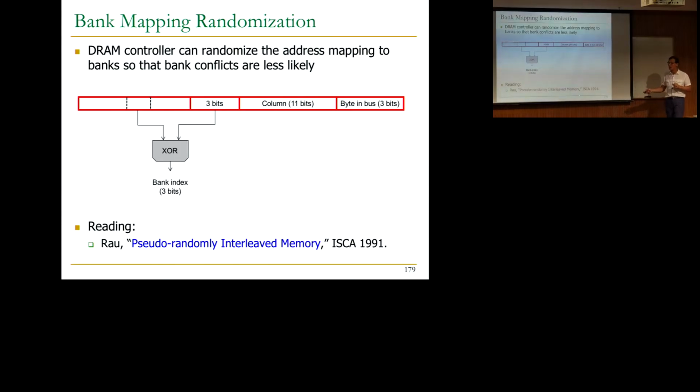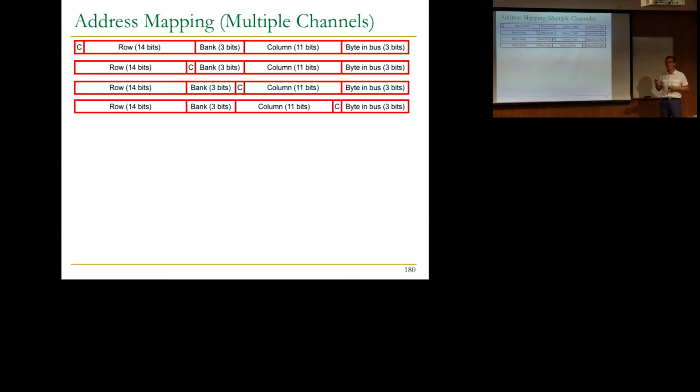And if you really want to know about this, this is a seminal paper that developed a good theory of how to interleave memory. And a lot of these techniques were actually developed initially for supercomputers because supercomputers were the ones that really pushed the need for the memory bandwidth. They wanted to get the highest bandwidth possible, and they realized that bank conflicts are really important. As I said, Cray1 was one of the first machines that actually had banked memory. It had 16 banks to cover the 11-cycle latency such that you could get 1 word every cycle. But even that was not enough. They needed to actually deal with bank conflicts, and Bob Rao talks about supercomputer memories in this case. Okay, let me keep going.